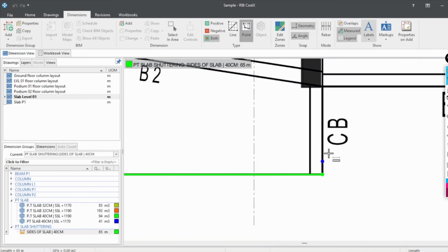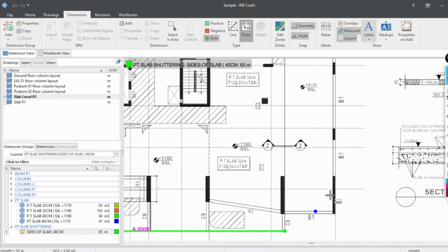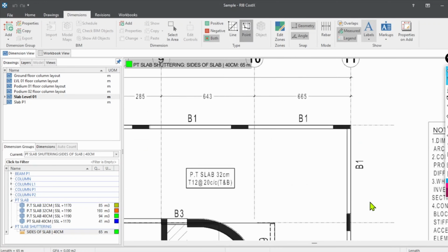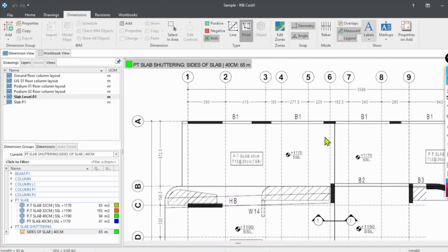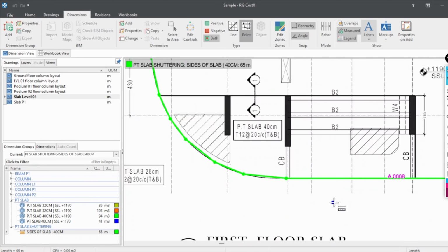See here, I'm not marking because this slab is supported by the beam. So I'm leaving this area. I'm moving on to the next area. Just keep looking on the edges. It's all supported by the beam. All supported by the beam. So wherever the free end, we mark.